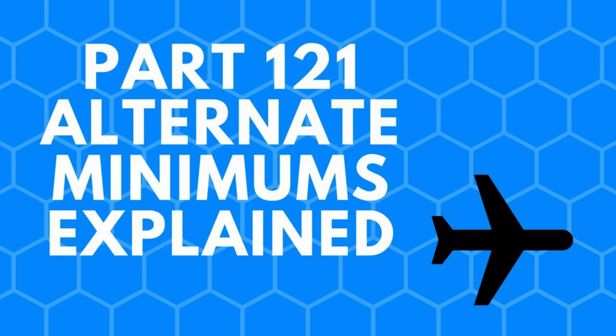Part 135 operators are also subject to their own specific rules regarding the selection and use of alternate minimums as outlined in their op specs in 14 CFR Part 135, Section 135.219 through 135.225, which are similar to those used by Part 121 operators with additional considerations.